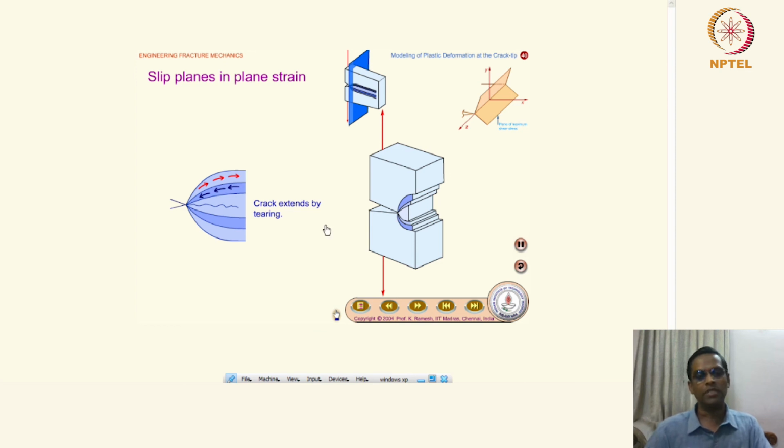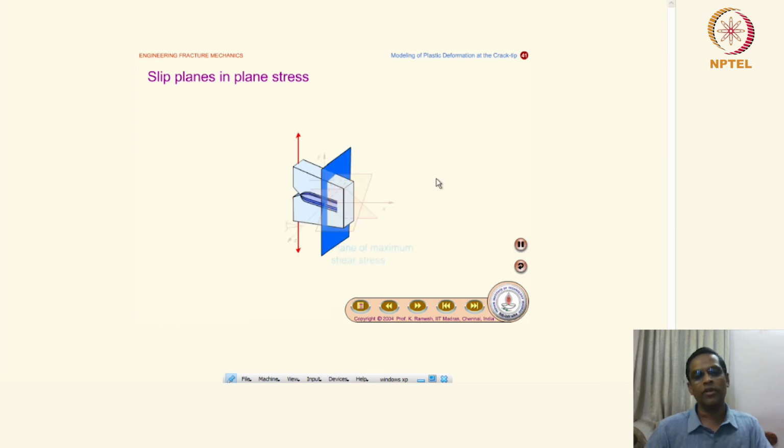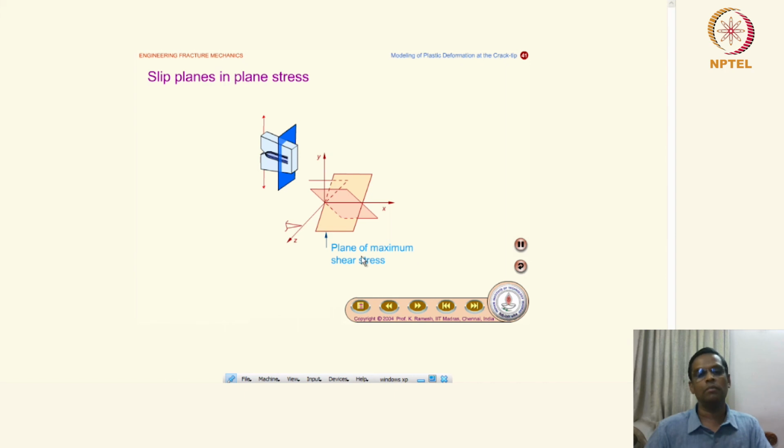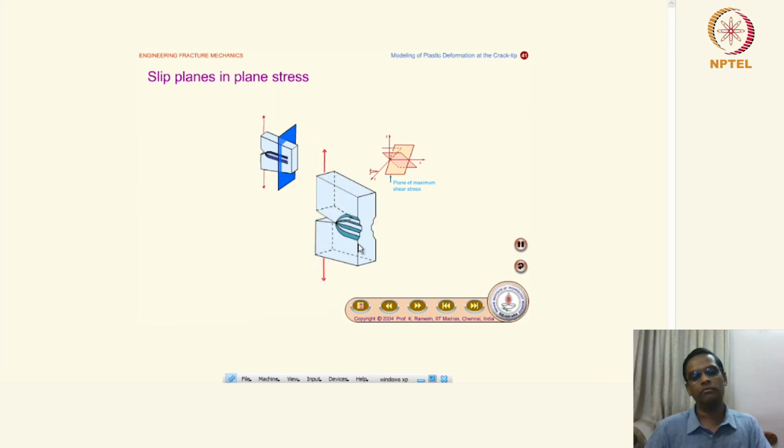And then what happens slightly interior to the plastic zone? It is quite different now. You see that the plane of maximum shear stress is something similar to what we have already seen. These are 45-degree planes, which are not in the same plane as the stress axis, but you can see how the 45-degree plane moves in this zone.